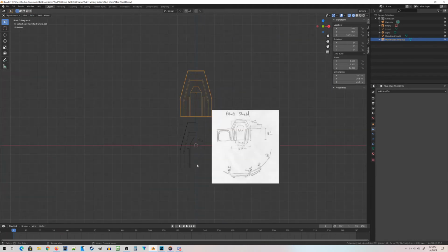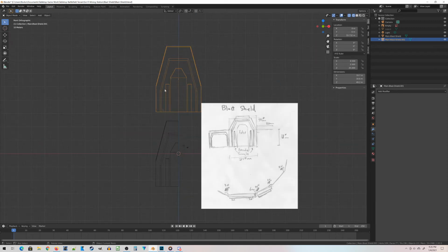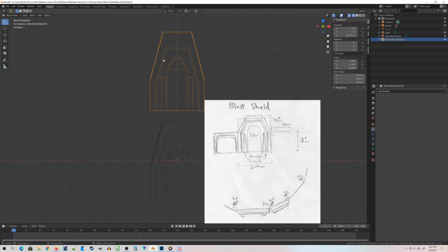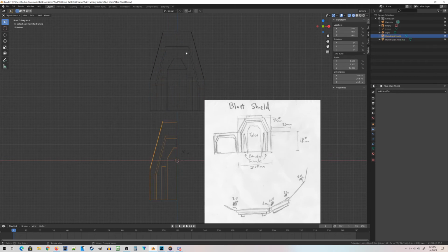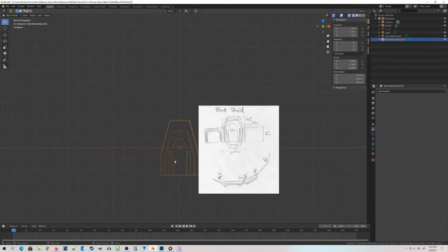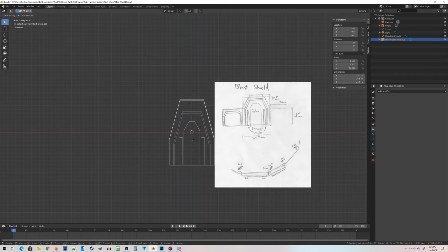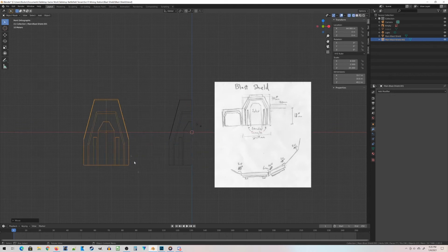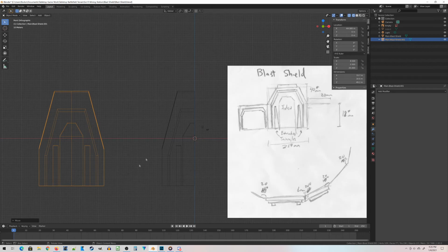So now what I need to do is move this guy over here at some point and set him off to the side. So I need to line this guy back up with this one. So this guy down here, we have a Z of 0. Let's left click on our copy. We're going to give it a Z of 0, yes. So now they're directly on top of each other. I'm going to press G and then X, and let's move them over this way so that I want about 35 millimeters or so between these pieces.